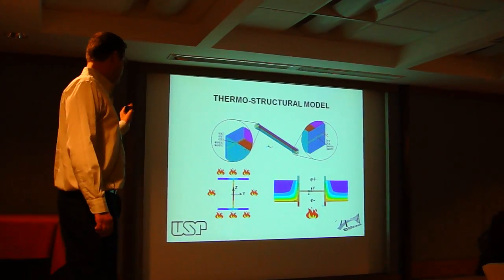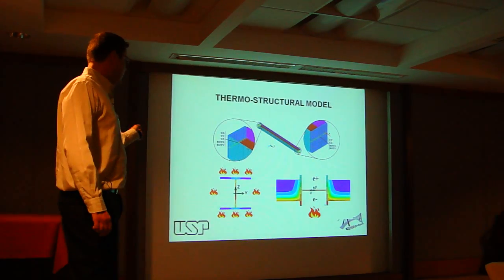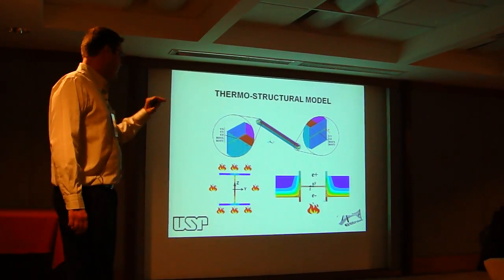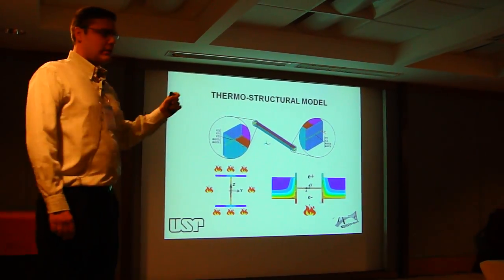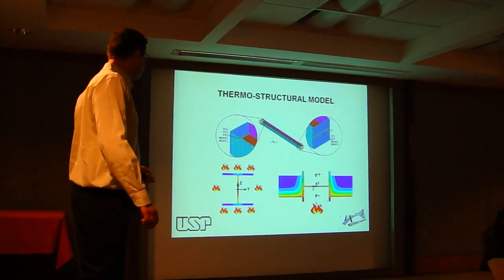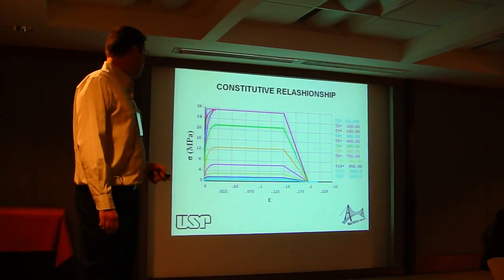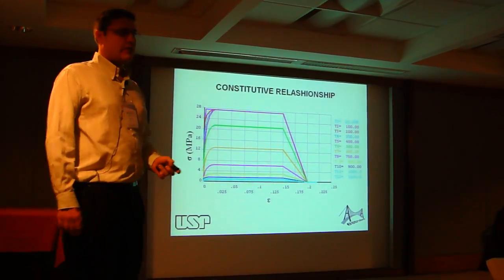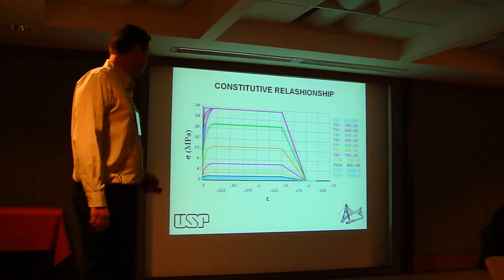The 2 models, the first without walls and the second with walls reaching the flanges, consider the geometrical imperfection, positive and negative. The constitutive relationship for the steel is that recognized by the Eurocode 3.